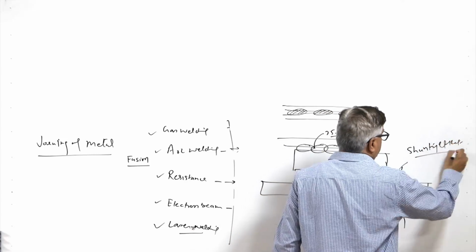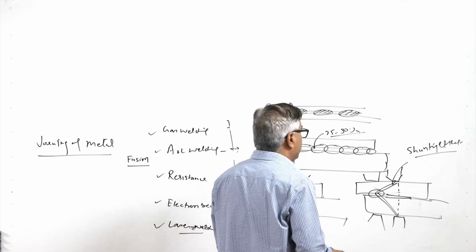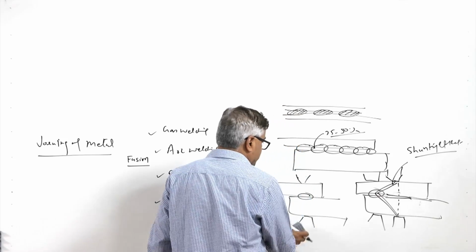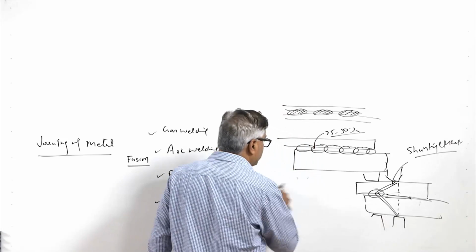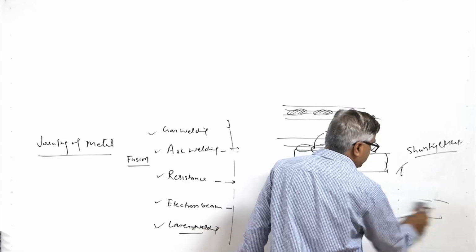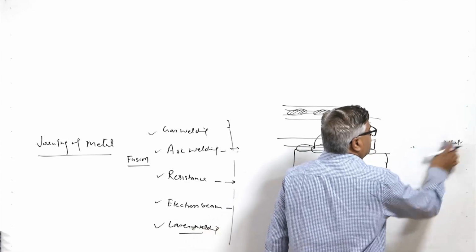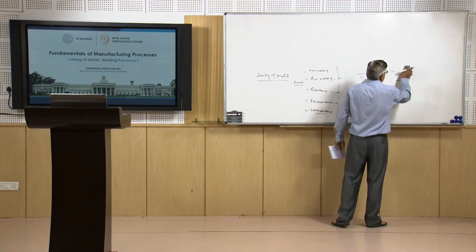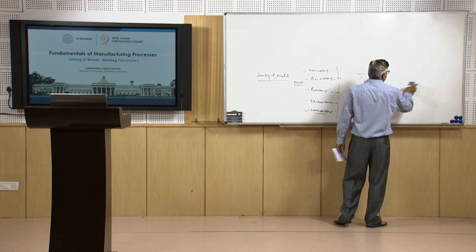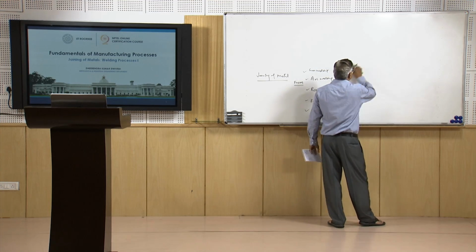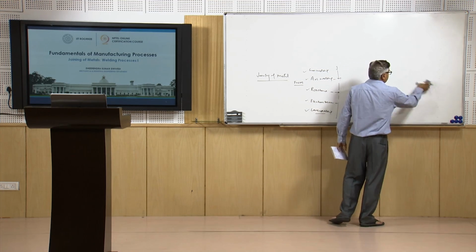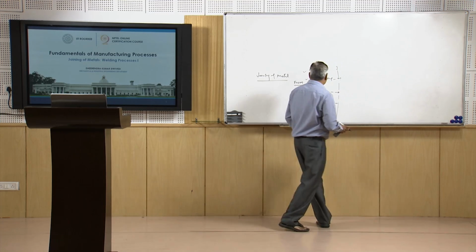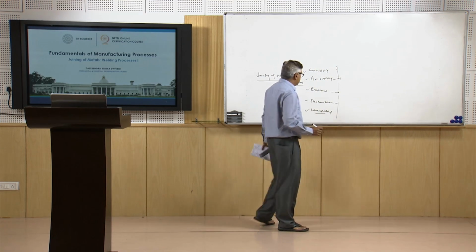because of which much higher current is required when a number of spots are to be made. That is why, when a seam weld is made, the requirement of welding current increases too high because of the increased shunting effect due to the continuous overlapping spot development during welding.